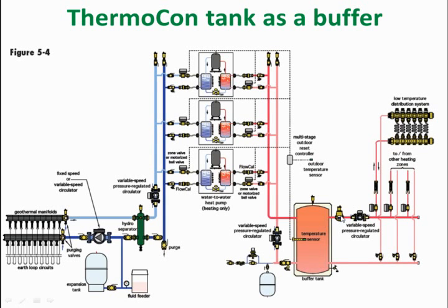We've got a Discal air purger there. We're doubling up on the air purgers here. Typically, this is enough air purger, having this one on the dome, the high point of that tank. Sometimes if you've got a system that has a lot of ups and downs or a lot of small diameter tubing, it's nice to put another air elimination device like a Discal in there, because that'll assure that this pump is never going to have air bubbles or have the potential to cavitate on you.